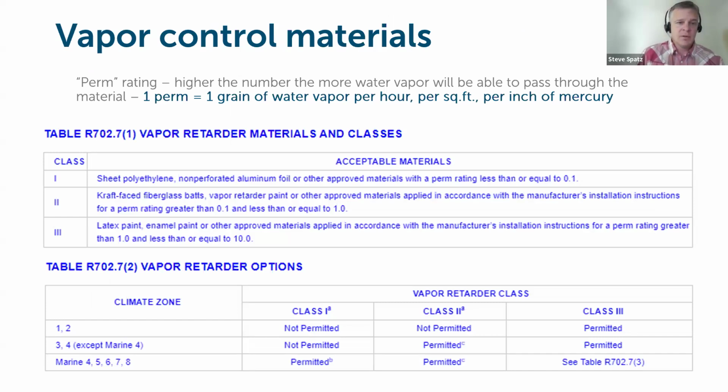So the idea of a vapor retarder or vapor control layer is to retard, mitigate and limit as much as possible the flow of moisture vapor through diffusion and air leakage into the assemblies behind it. The diffusion is the piece of what the vapor retarder is intended to mitigate against. But if you're not installing that vapor control layer with consideration of the air that can get behind it and air leakage around the plane of the vapor retarder, then you are eliminating the potential of that material to do what it was designed to do.